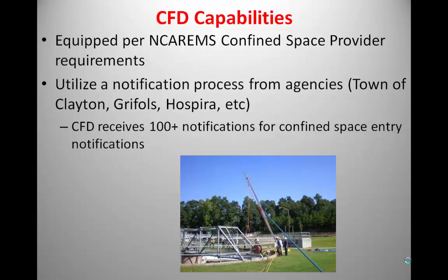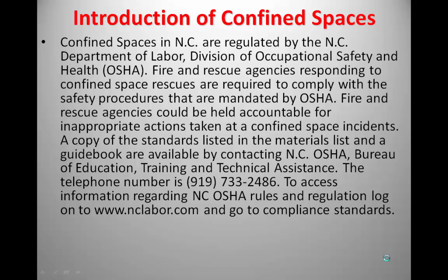And on the other side of that as well, when we do training, we also notify these entities that we're doing the training, so they have the opportunity to come out and evaluate us on our skill proficiency, which is an OSHA requirement. Well, it's an OSHA option. The 1910.146 standard specifies that it's a non-mandatory option for employers to evaluate their rescue services. So there's just another option out there.